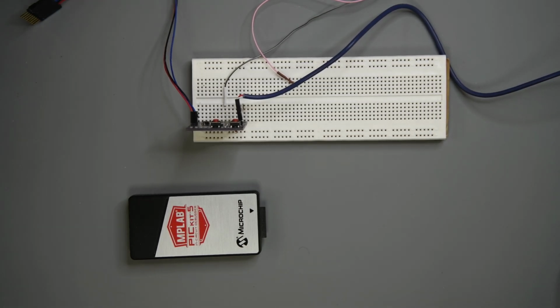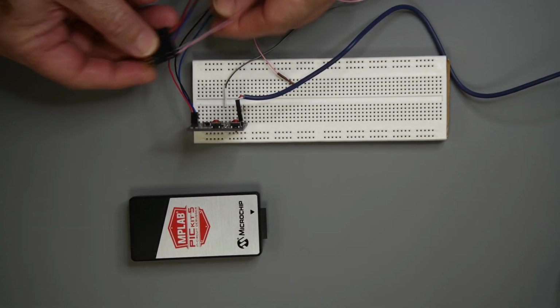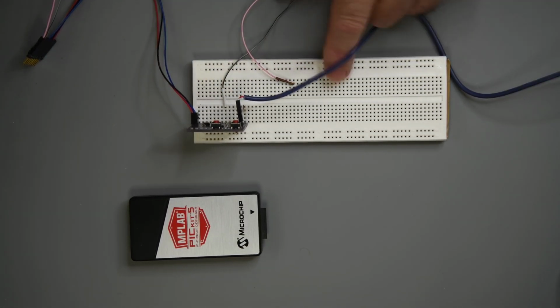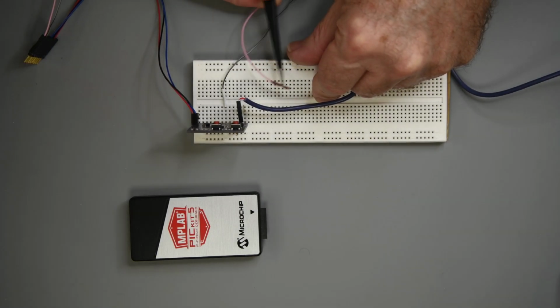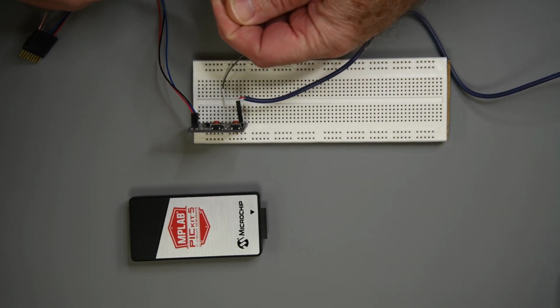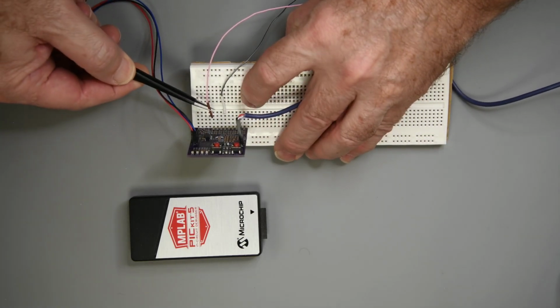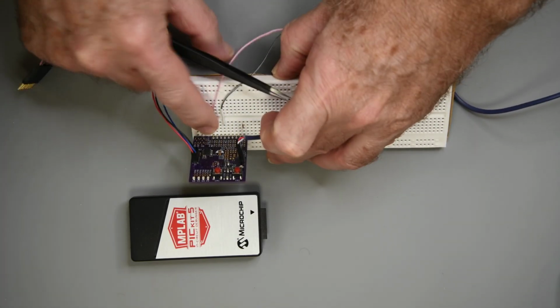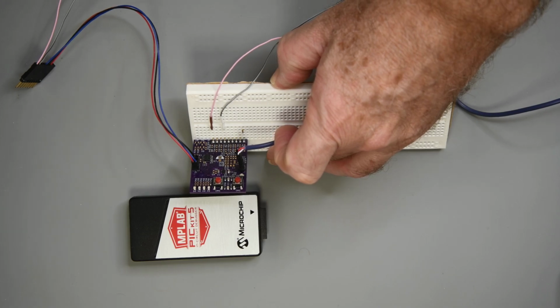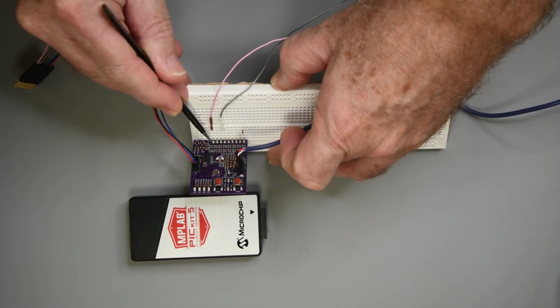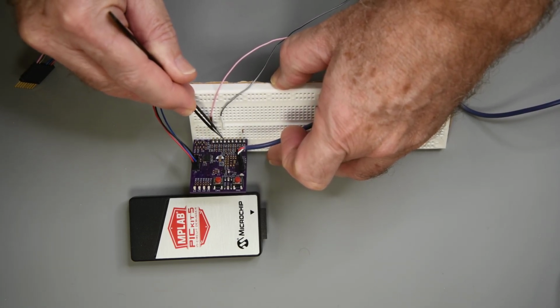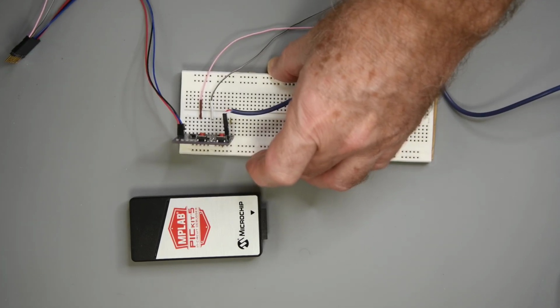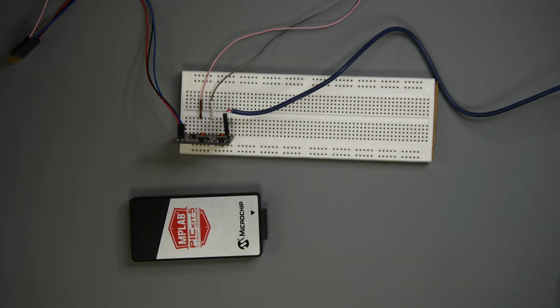Last time I was only using pin 7 of the PICkit 5 data streaming interface. Now I will need both pin 7 and pin 8 connected, pin 8 being the data output from the PICkit 5. So pin 7 of the PICkit 5 will connect to PA6 on the ATtiny402, and pin 8 of the PICkit 5 will connect to PA7. That should be it for the hardware changes.